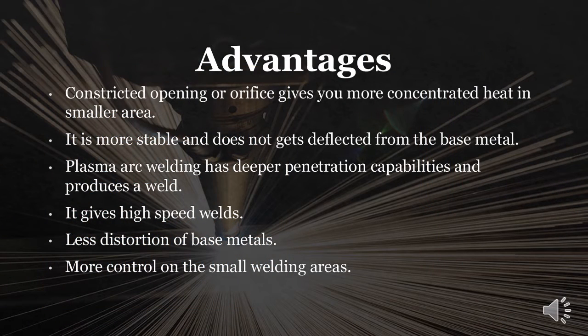There are some advantages of plasma arc welding. First, the constricted opening or orifice gives you more concentrated heat in a smaller area. Second, it is more stable and does not get deflected from the base metal. Third, it has deeper penetration capabilities and produces a weld. Fourth, it gives high speed welds. Fifth, there is less distortion of the base metal, and then more control on small welding areas.